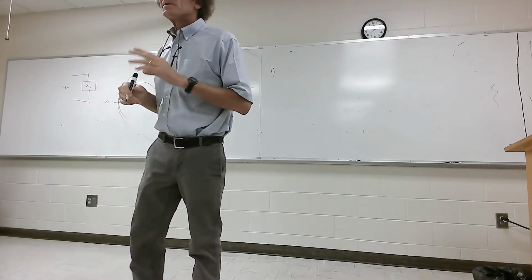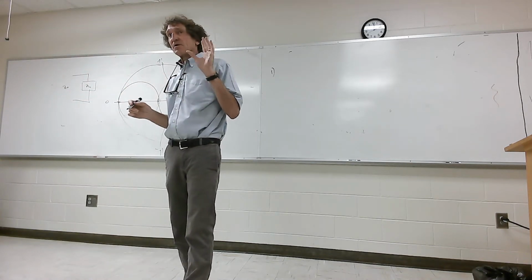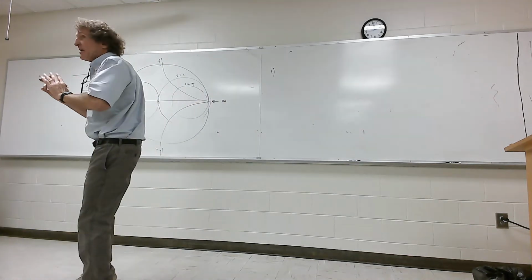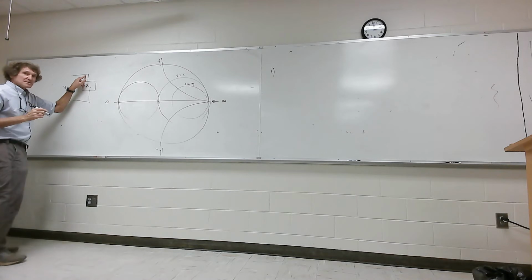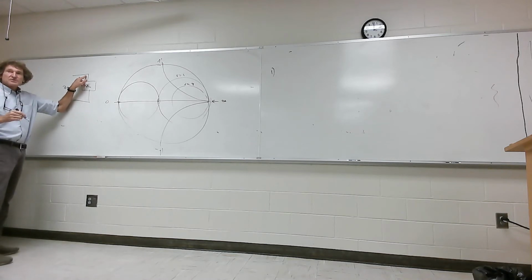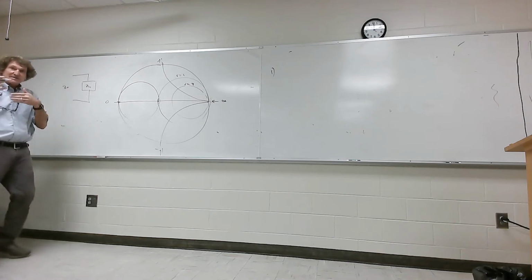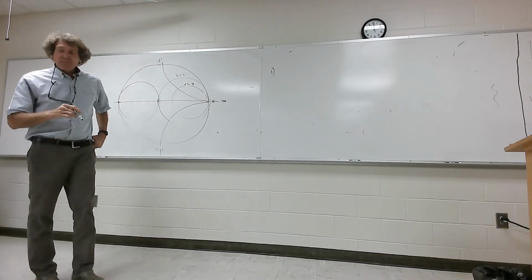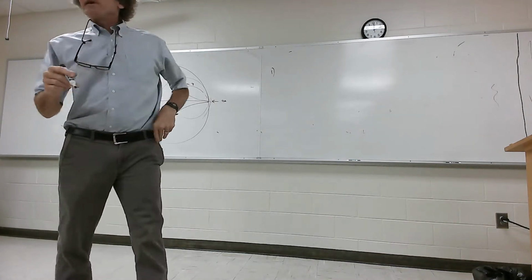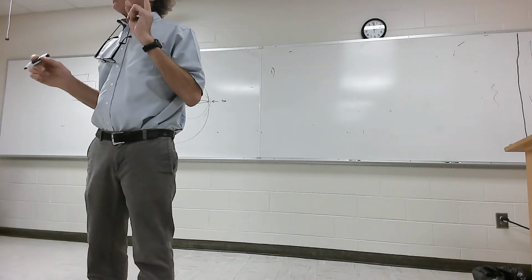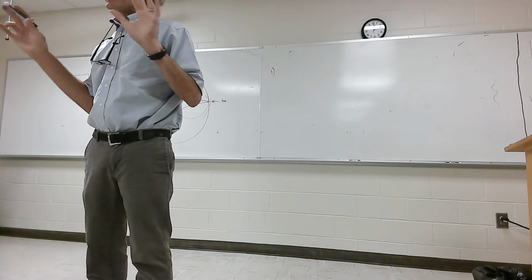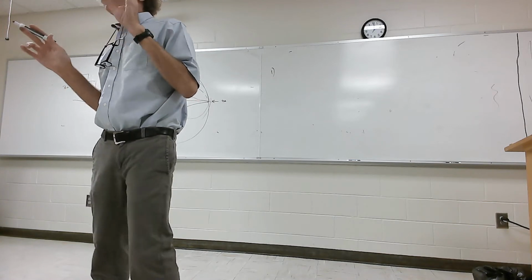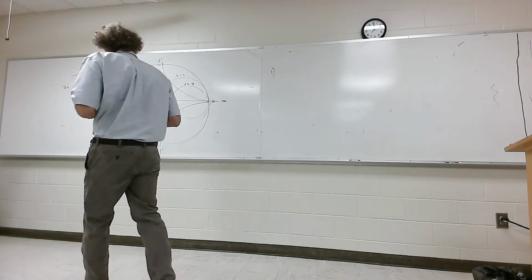Now I'm going to show you something. This is called L-section matching. The goal is to not have to have any kind of length of line. We're going to put all these elements right next to the load so we minimize the use of space on that board. We want everything up snug. We don't want anything any distance apart. But the thing you got to remember, this is only at one frequency. This is not wideband matching. That's a completely different animal, and that's something we don't even take up in this class. But this is going to be for narrowband matching applications.